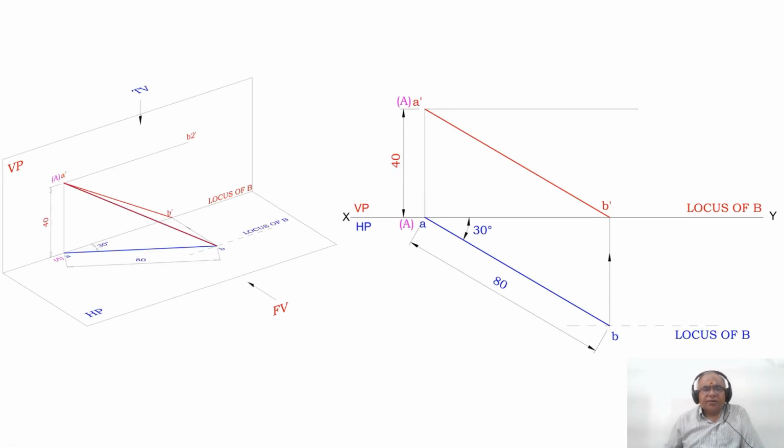So then how to do that? By using manual drawing. Here, with B as center, since you know the locus of B in the front view and also the locus of B in the top view, we have the end projector A. We know that this is the top view point, so obviously the front view point should lie on the same line. Since you have the locus of B in the front view, draw a vertical projector from B to the xy line in the front view, and mark this point as B dash.